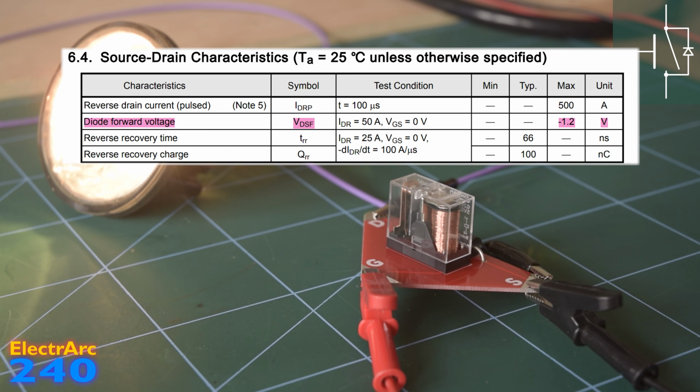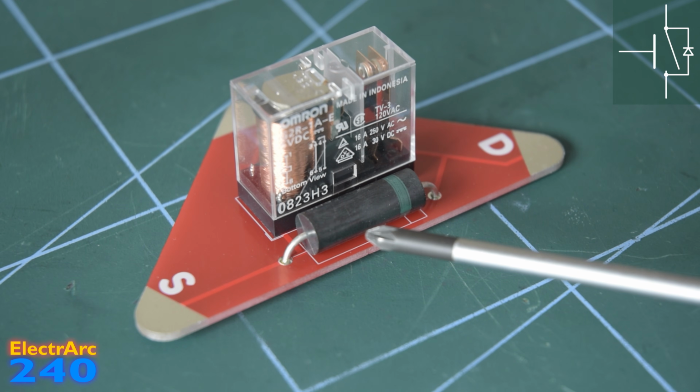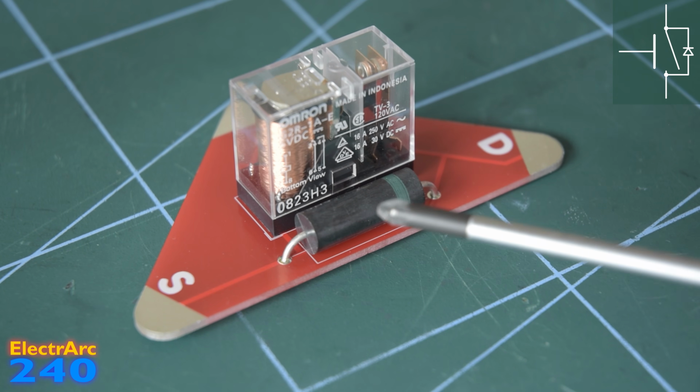And here you can see the forward voltage of the diode in the datasheet. This varies a little bit with current, but essentially it's a fixed voltage drop that you're always going to have with current flowing through this body diode. And in almost every case, this is going to be greater than the voltage drop you'd have across the channel. So, is the body diode a problem? I'd say generally no, and in some circuits it's even useful to have. But there are definitely one or two situations where having it is annoying.